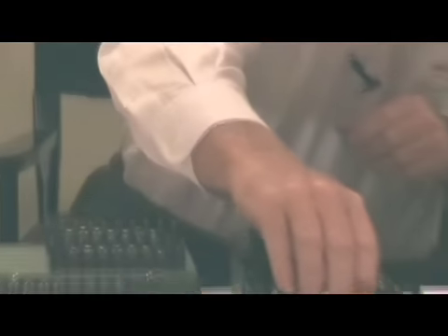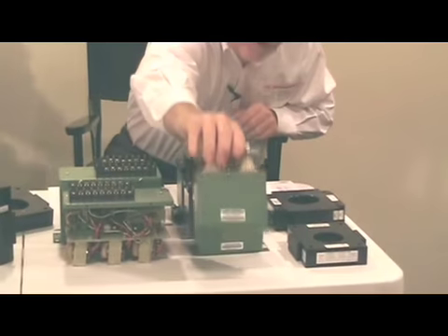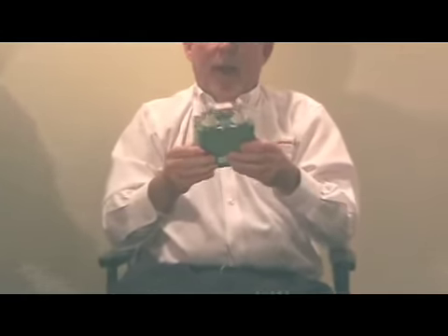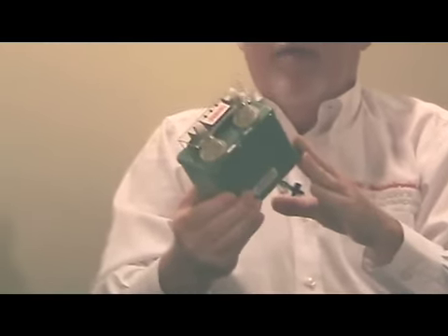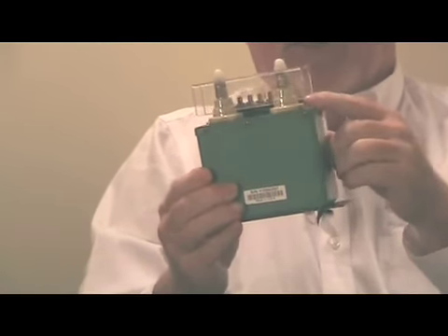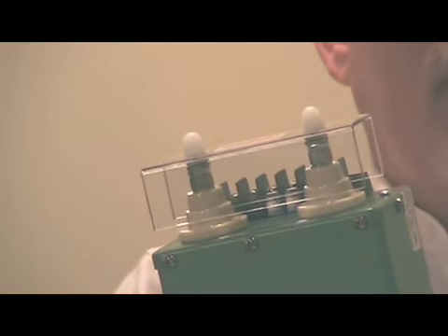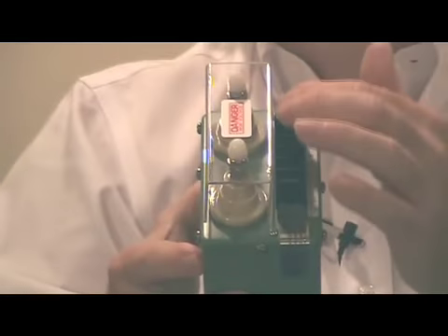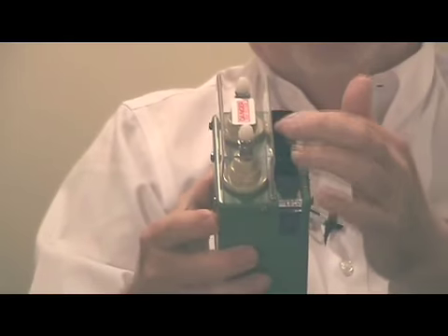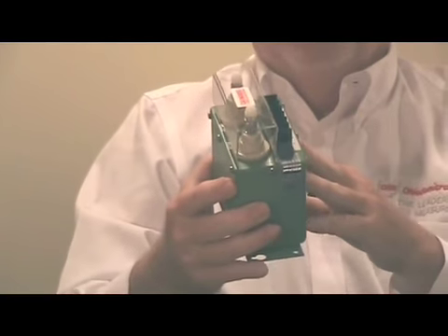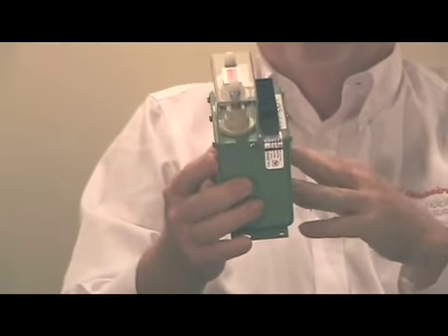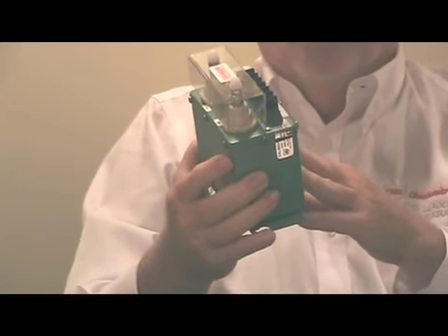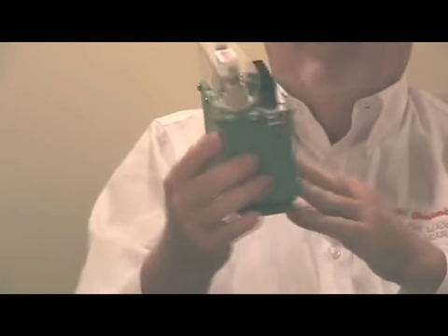We have a customer, for their use on board a ship, it happens to be a military customer, they required the use of these ceramic insulators and a protective cover on it. And I'm assuming it's for some kind of safety rating on board the ship. Again, we still have the terminal strip for our outputs and instrument power, but for the voltage input, which I believe is in the 600 to 800 volt DC range, they require the use of those ceramic insulators.